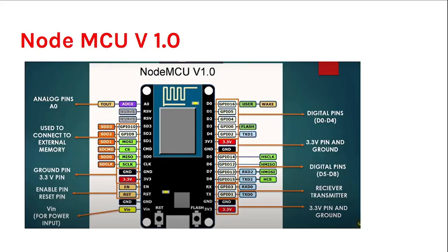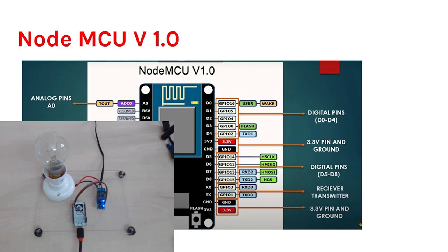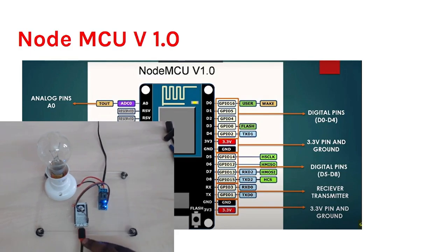Coming to NodeMCU, for the pinouts I'm going to use D2 today. I'm going to connect one relay here. As for the wiring part, I'll show you the hardware. I have a NodeMCU to which I have connected a single channel relay board, which is connected to the D2 pin. The single channel relay board has 3 wires: VCC, ground, and the data, for enabling and disabling this relay.